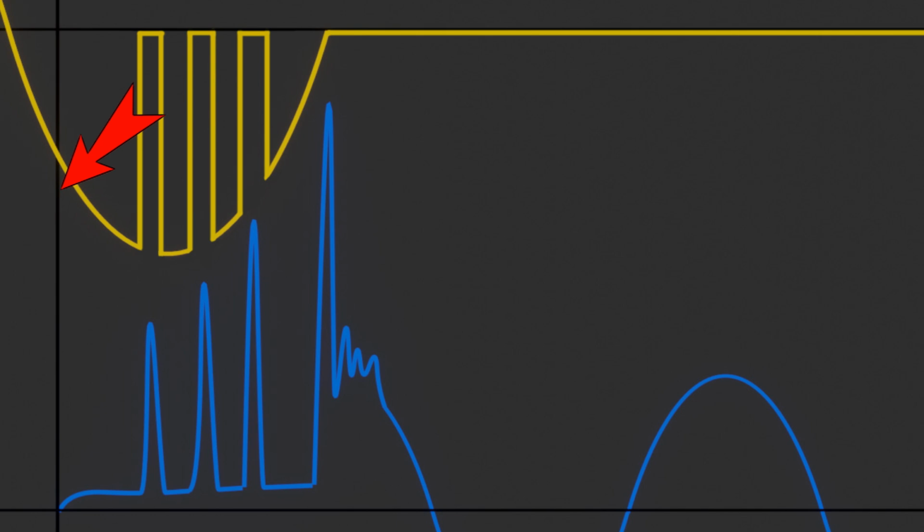This is the instant when the circuit breaker starts opening. This is the instant the current was chopped. This is the restriking voltage. Due to this restriking voltage, the dielectric medium, which had been re-established, again breaks down, and the arc starts again. Then the voltage between the contacts again drops to arc voltage.